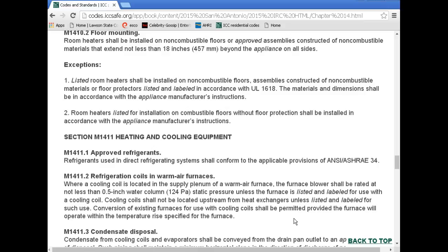You go, hey, I need backup heat. You cut the gas heat on. That gas furnace is 130, 140 degrees. It's warmer than the heat pump. The heat pump can no longer reject heat there. That's why a heat pump cuts off when you cut up your backup gas heat. And if you have strip heat, guess what? It's downstream of the coil. Okay? All right.